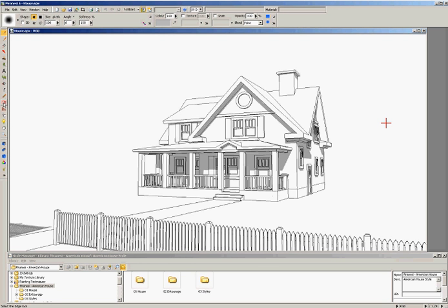It's fairly self-explanatory. The difference with Piranesi's Find Edges tool compared to something like Photoshop is that because we're able to use find edges on the basis of depth and also material, we can pick up the absolutely pixel perfect edges, whereas something like Photoshop might be working off the difference in the color ranges for each pixel and assuming that a large color jump would represent an edge within your image. We don't have to rely on that within Piranesi. We can do find edges by color, but it's much more accurate if you can do it on the basis of material changes or depth changes.